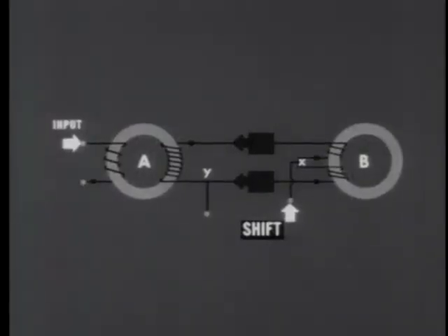Schematically, this loop resembles the one we've just been studying. There's the same split winding arrangement to which the shift pulse is applied, the same diodes placed so they oppose the flow of current out of either side of the output winding, and the same outlet connecting into the loop at the non-dot side of the output winding. The differences are all on the left.